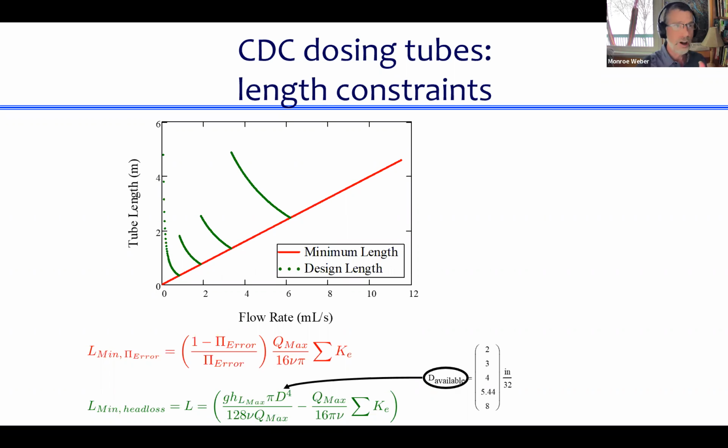And you should always be wondering, well, why was 20 centimeters chosen as the perfect design for AguaClara plants? If we go to more head loss through our linear flow orifice meter and through our dosing system, that ends up meaning that the head loss through the entire plant increases because all the water goes through the linear flow orifice meter.